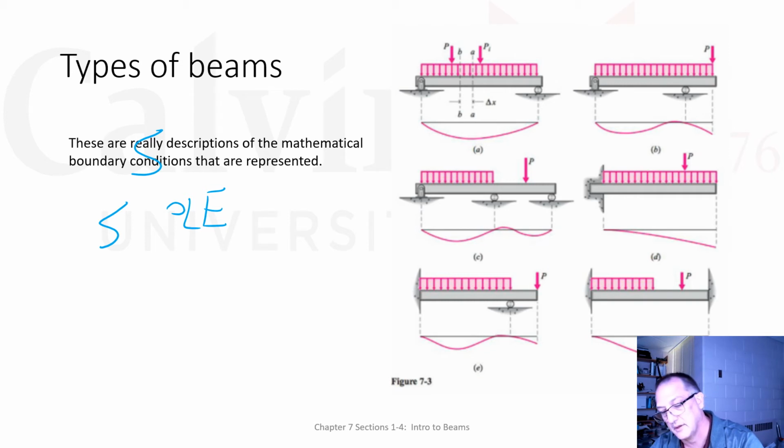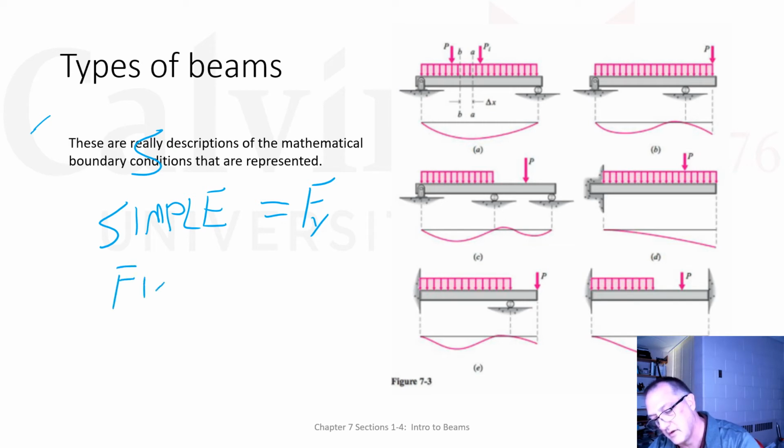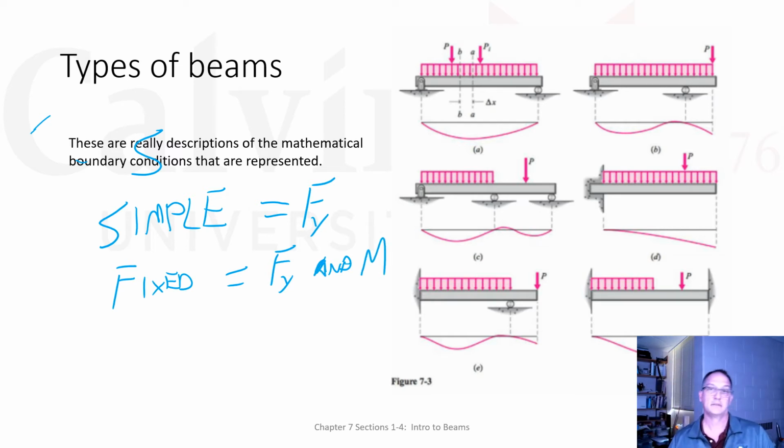simple, can't touch the screen. That word simple correlates to there's just a force in the y. And fixed means there's a force in the y and a moment. And so those words are used just to describe the mathematics of the boundary conditions.